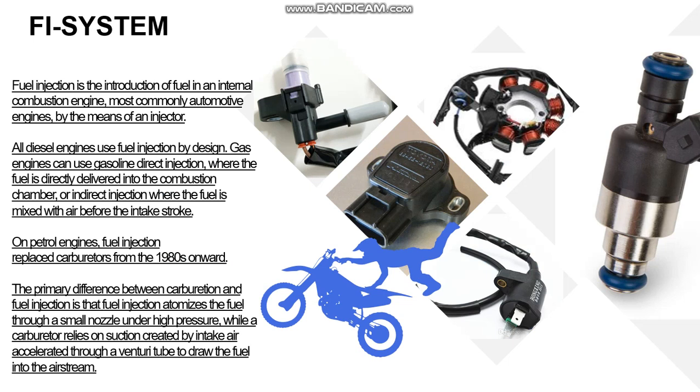Fuel injection is the introduction of fuel in an internal combustion engine, most commonly automotive engines, by means of an injector. All diesel engines use fuel injection by design. Gas engines can use gasoline direct injection, where the fuel is directly delivered into the combustion chamber, or indirect injection, where the fuel is mixed with air before the intake stroke. On petrol engines, fuel injection replaced the carburetor from the 1980s onward.